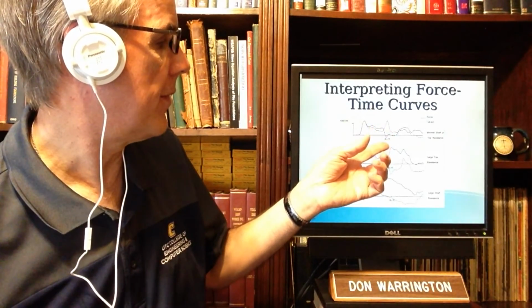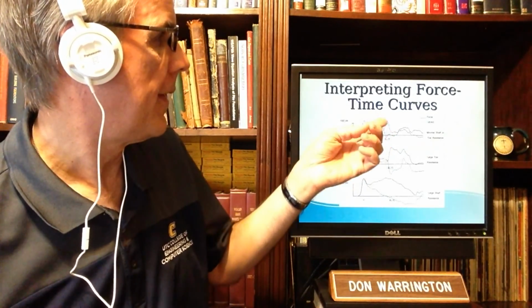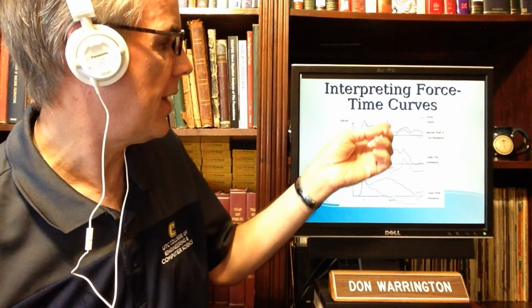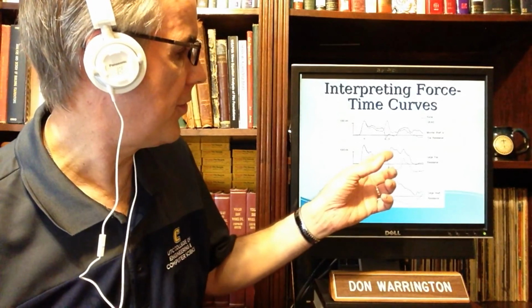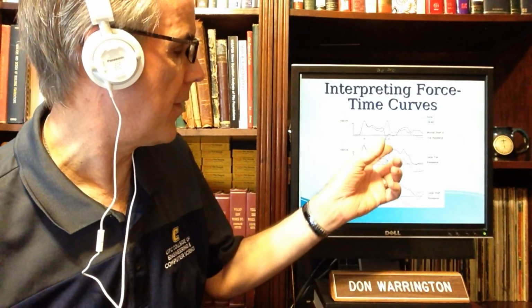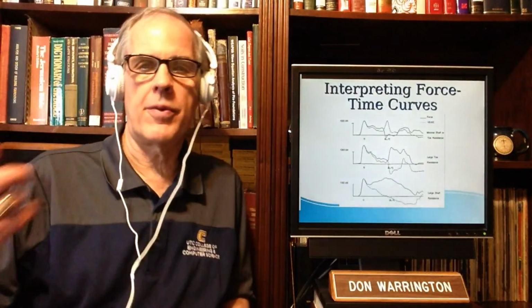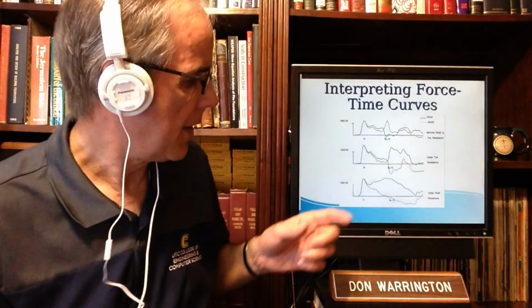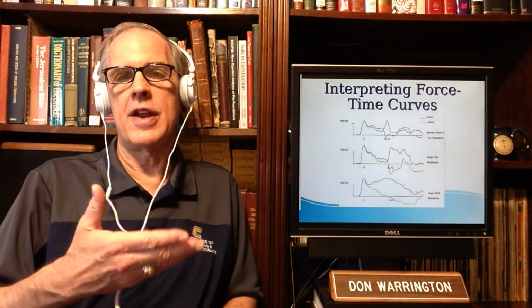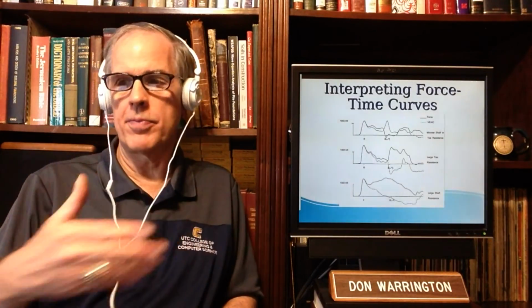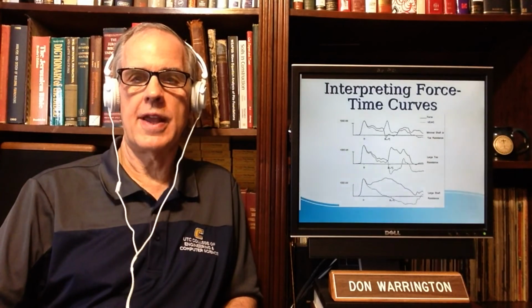You'll notice that the stress wave comes back up in tension, and it gives you this kick. With a large toe resistance, you get something like this, where you get that wave doubling effect we talked about in the pile wave demonstration. And last but not least, with large shaft resistance, the toe resistance gets wiped out. Again, this is an easier thing to understand if you look at it from the pile wave program demonstration I gave you.